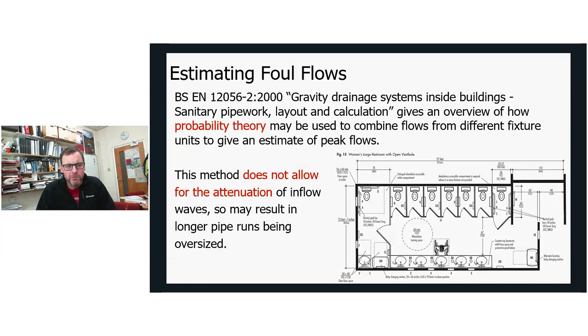Obviously, for industrial and commercial processes, you would speak to the users or do some research to try and estimate what the likely flows from those would be. Some commercial and industrial water users, even though they might be heavy users themselves, might offer, or a water supply company might ask them, to treat their own effluents where there are particular pollutants in them, or where there are really large volumes. So they can have their own treatment processes, and they can then have the right to discharge either pre-treated water to the sewerage network or treated water back to the environment.